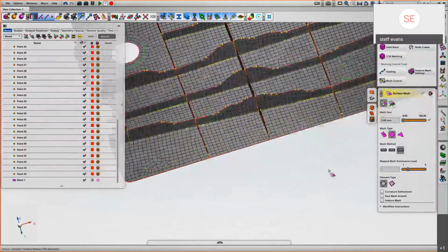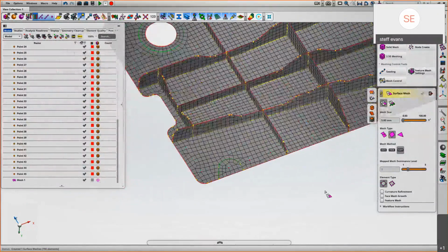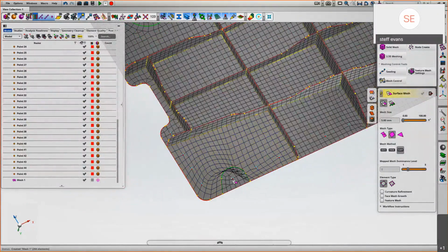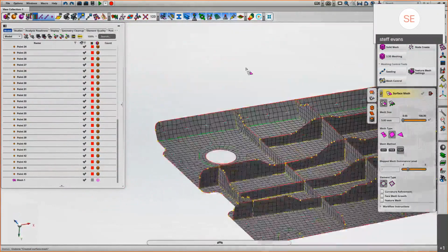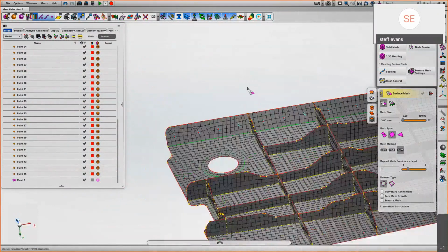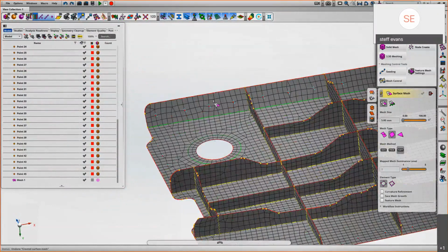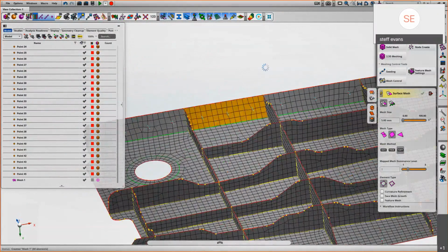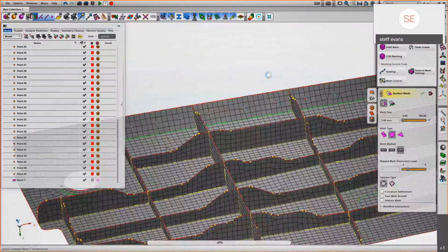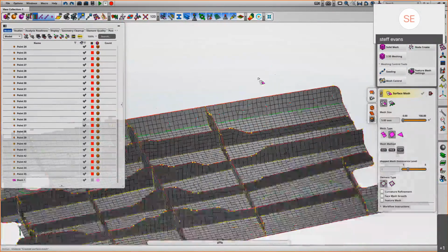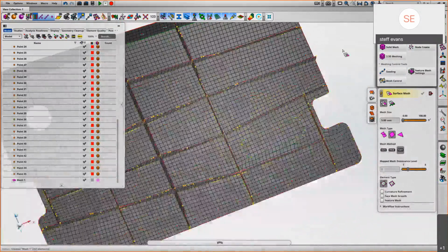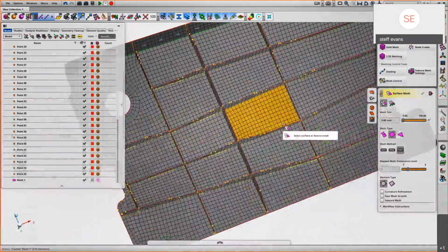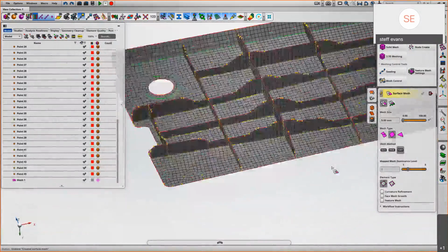Okay, so we've just remeshed a couple of portions of the stiffener. We'll remesh this edge surface or this edge face. You saw there the map mesher wasn't perhaps the best tool, so we'll stick with the mixed algorithm. And again here, because we've got a fillet corner on the left hand side, the mixed algorithm is probably the best to use. If we've got these nice square faces, we can just quickly remove the tries as needs be. We could add some more splits into the geometry to improve things if necessary. Okay, but we're just removing as much irregular mesh definition as we want.